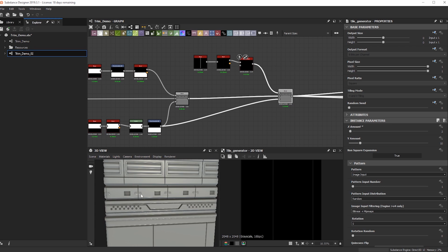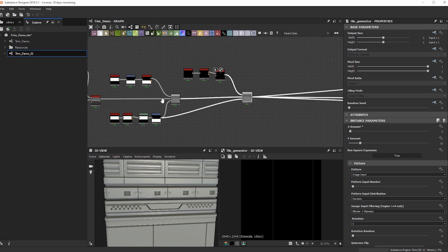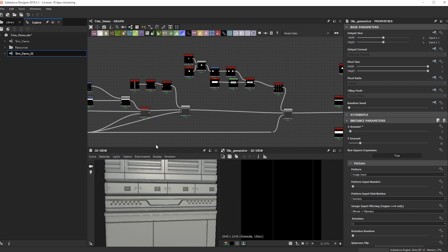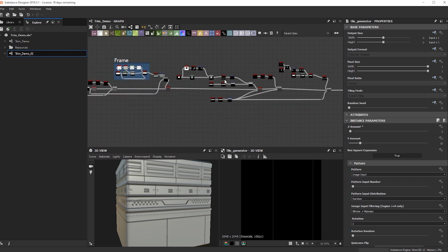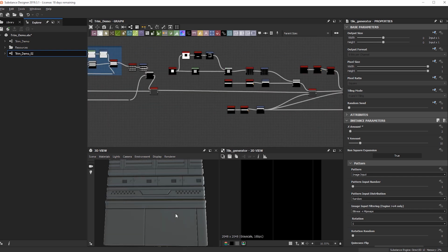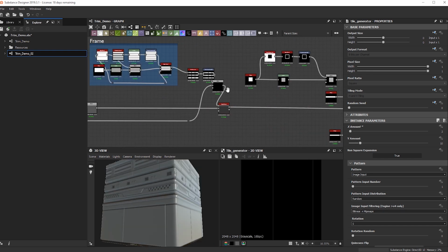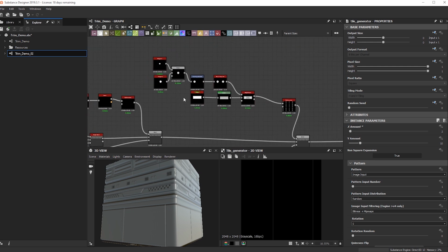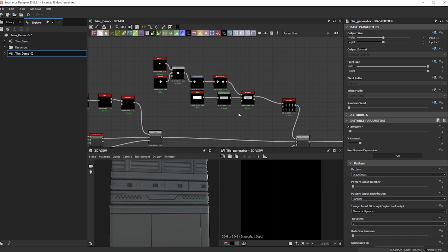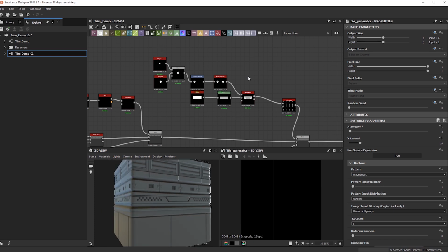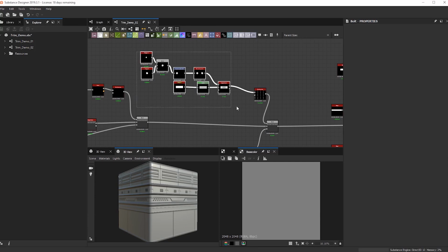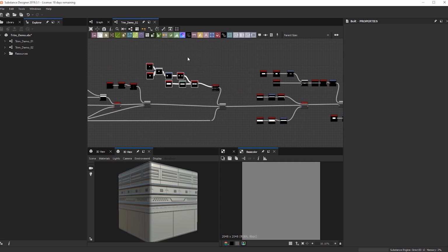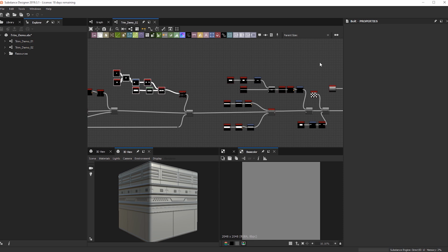The cool thing about getting these guys up and running was we have the ability to create pretty much tools within Substance Designer to be brought in later on as a single node. Now, this is the one little section I'd like to show you guys. For example, if we go back to this bolt treatment that we did here, what if we wanted to integrate this and make this into a single node? That way we don't have to constantly keep copying this graph and bogging down and making duplicates of the same kind of nodes. We can simplify it into a single node and then just use it accordingly.